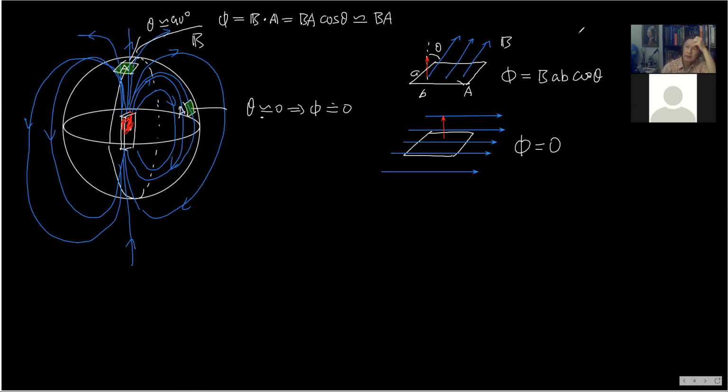Okay, let's go to something real. That is an electrical generator, right? If I draw this diagram for you, this is a 3D diagram, because a 3D diagram can be easily understood. But you have to get used to that. Sometimes we use a 3D diagram, sometimes we use a 2D diagram. So this is just part of the magnet. On the other side, we have this curved shape. The reason we use this shape is to make the magnetic field uniform in the gap, you see? So that would be the south.